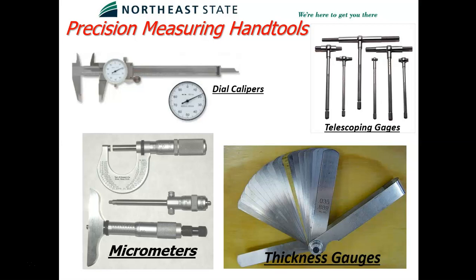What I mean by that is on the outside and the inside micrometers, the top and middle, your 0 is on the left, and it goes 0 up to 9. On the depth micrometer, your 0 is on the right side, and it goes 0 to 9 on the scale from right to left. But you read it just the same.